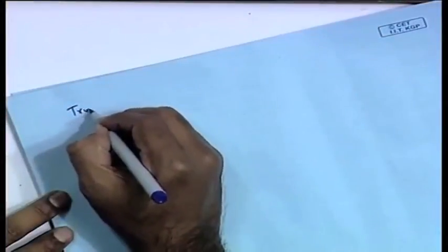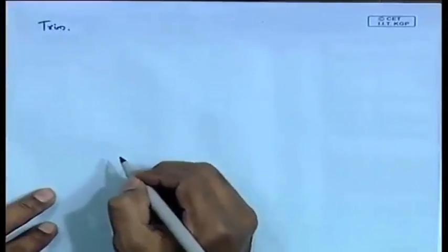Okay. So, in the last class we talked about the TPC, TPI, that is the tons per centimeter immersion and tons per inch immersion, the amount of weight that needs to be put to produce a centimeter of submersion of any body. After this we will now take a look at some other phenomenon that goes along with this. This is known as trimming. So, trim is a phenomenon that is associated with a longitudinal submersion.